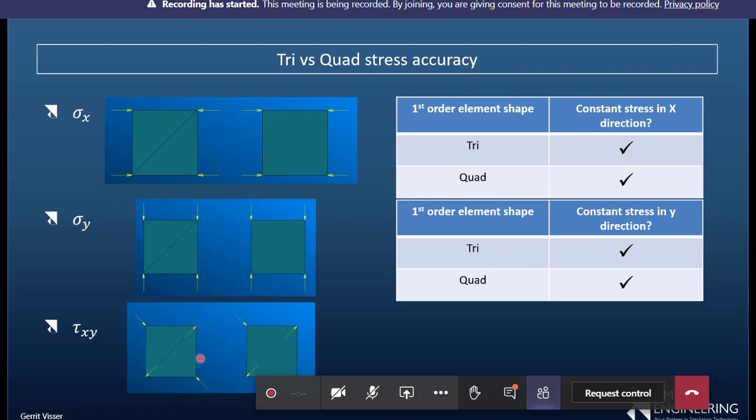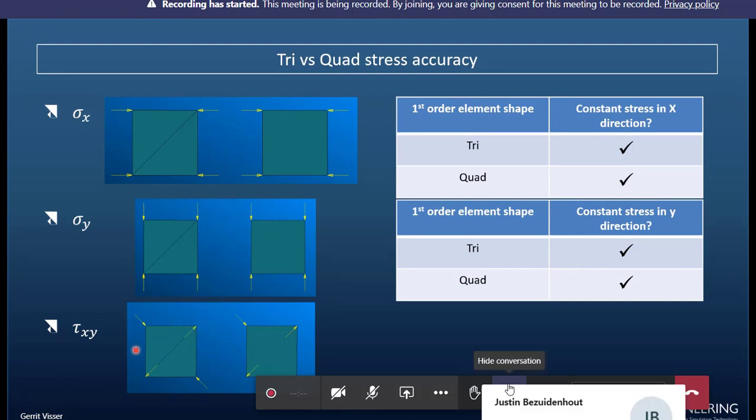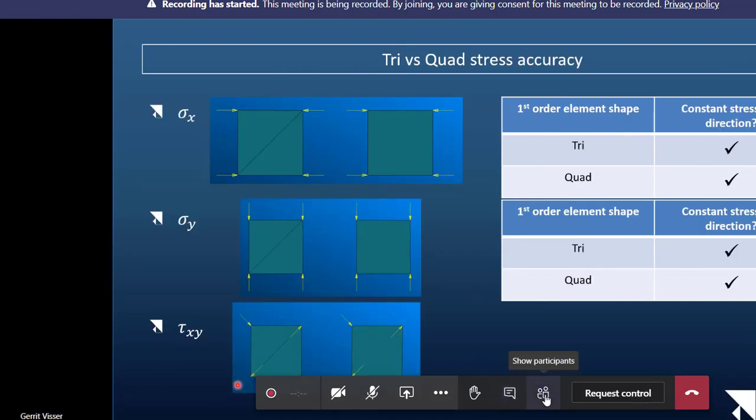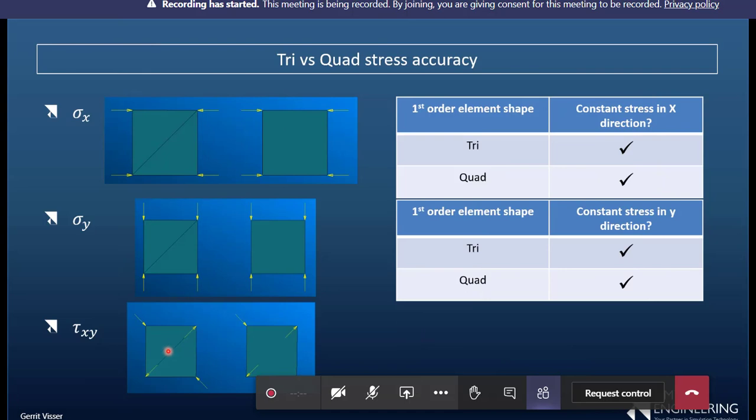Shear, okay, I know you're probably not too familiar with this definition of shear. Think of it this way. If I apply a shear load in this direction to the right and at the bottom to the left, then if you look at that very small local part of material, there's also a force in that direction which matches this one, and one down that matches this. So this is simply a different way of looking at shear stress.